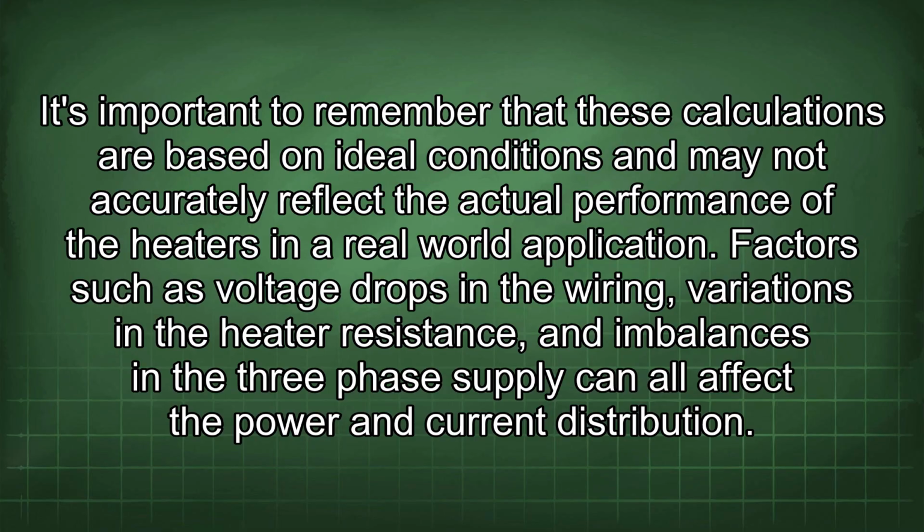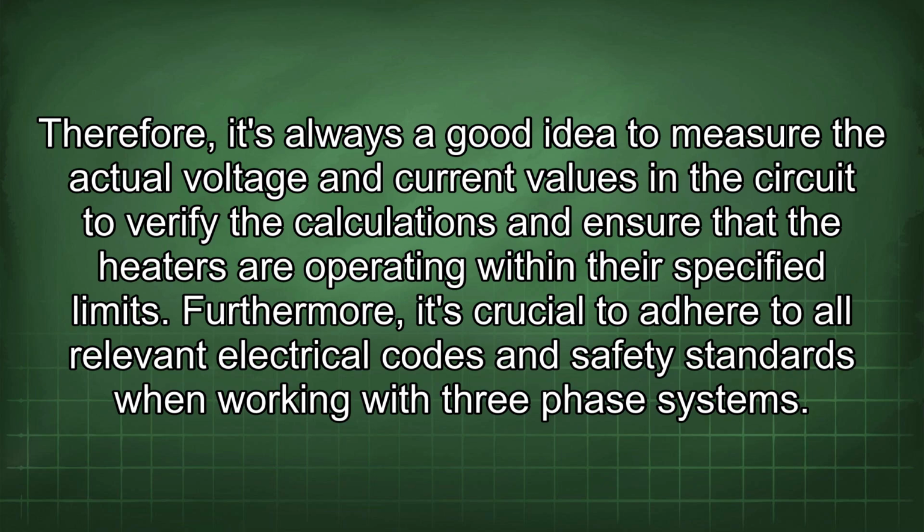It's important to remember that these calculations are based on ideal conditions and may not accurately reflect the actual performance of the heaters in a real-world application. Factors such as voltage drops in the wiring, variations in the heater resistance, and imbalances in the three-phase supply can all affect the power and current distribution. Therefore, it's always a good idea to measure the actual voltage and current values in the circuit to verify the calculations and ensure that the heaters are operating within their specified limits.